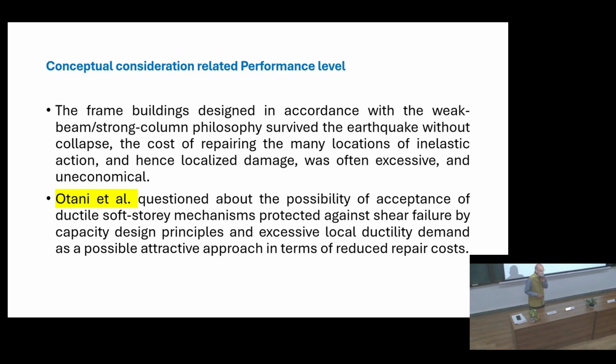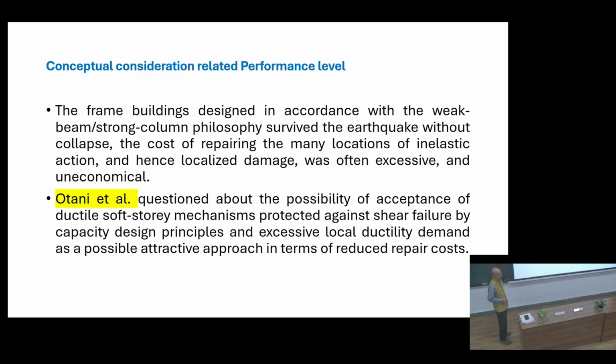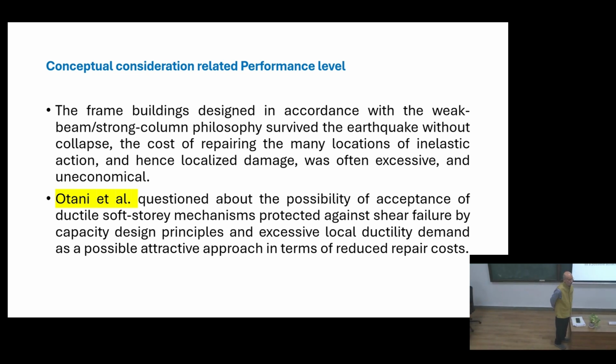That may not be economical, and you may need to replace the entire structure. So it does not work all the time. You have to see, at the design level, how many plastic hinges and at what locations you are expecting them. The sequence of formation of plastic hinges is equally important. That is what performance is.